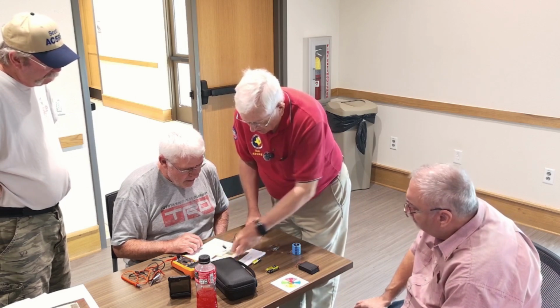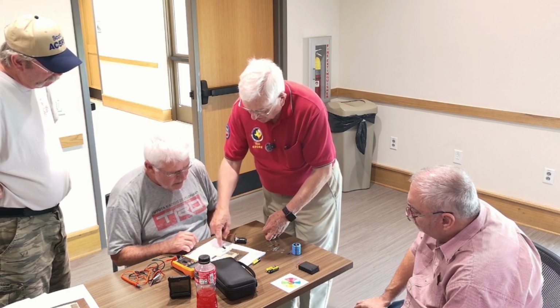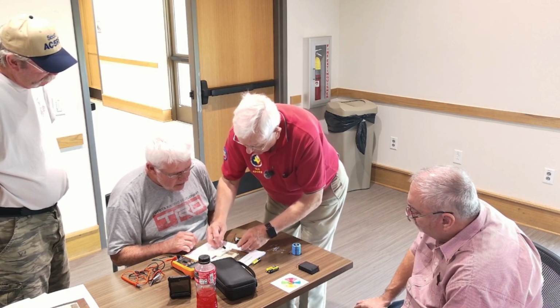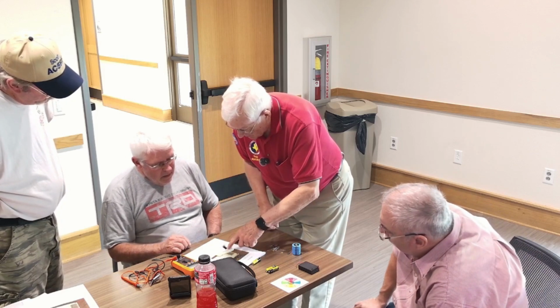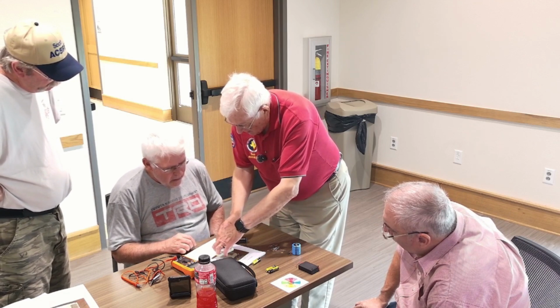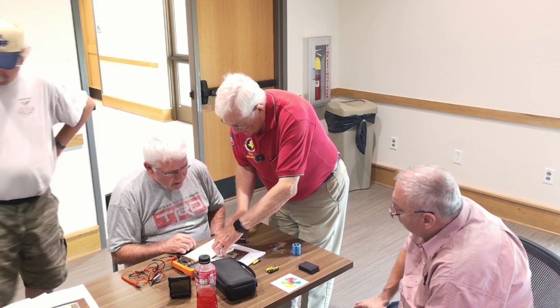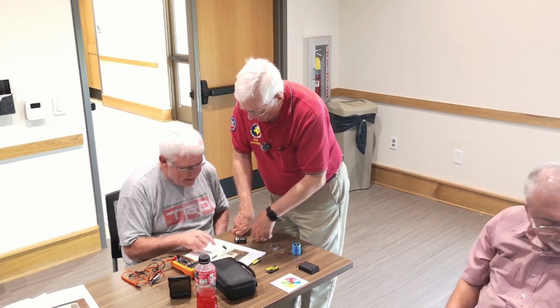And then we're going to take that resistor, and we want to connect this resistor between here and the positive leg. To do that, we just plug him in right there, same in that row of 5 pins. All 5 of those are connected together. And then we hook this guy to there. I can put him in any one in that row because those are all hooked together. That's all positive, and that's all negative.